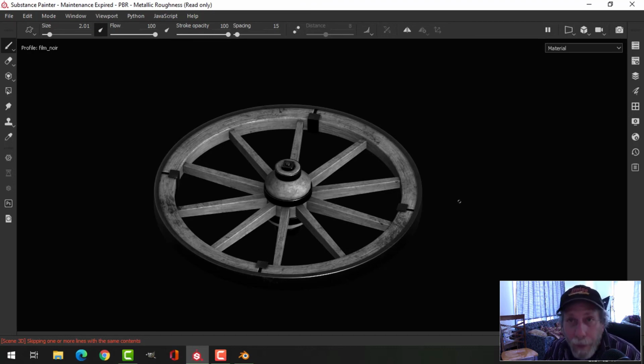But very quickly, we have shown that we can use Blender alone, on its own, just a UV unwrap. We can try Smart UV Project. We can straighten some of our UVs. We can add a very, very simple seam across this. We didn't even really UV unwrap the metal. We just let Blender do it.